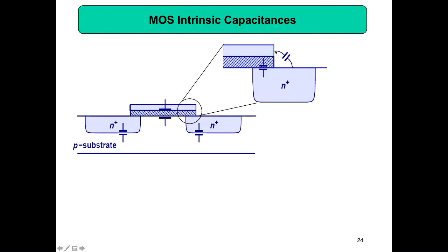So then there will be a small effect like a fringing field capacitor. A capacitor is formed due to the fringing field. So whenever there is a voltage difference between 2 points, you get a capacitor effect. And if they are not in parallel, if both are aligned, then you can say in between you got a capacitor. But even if it is a bit shifted, the electric field can go from positive to negative. So that is called a fringing field, a capacitor due to the fringing field.